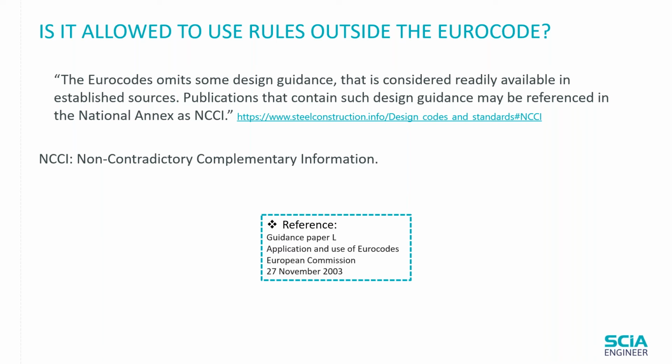For this, we would like to reference the guidance paper L on the application and use of the Eurocode, which states that the Eurocode indeed sometimes omits some design guidance, like calculating M critical, and that they consider there are established sources available, and that those sources and publications can be used as long as they give non-contradictory complementary information. So information that adds to the Eurocode and doesn't contradict it.